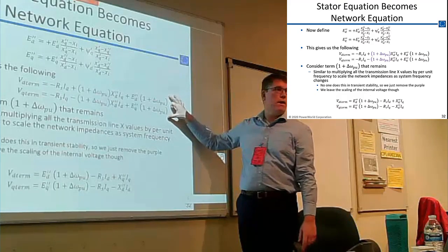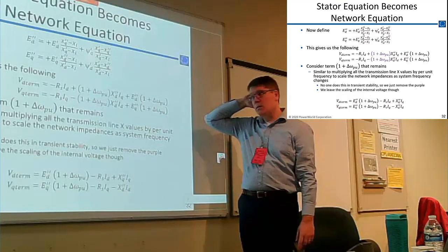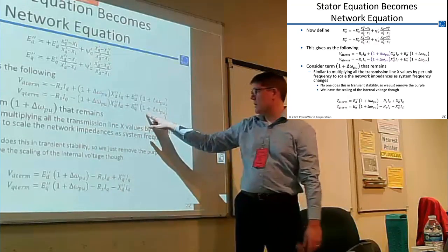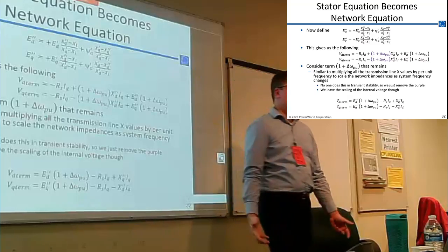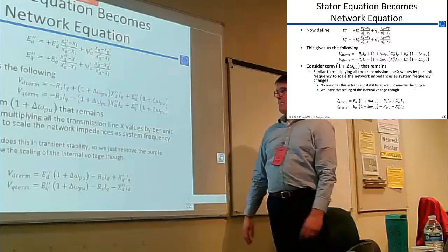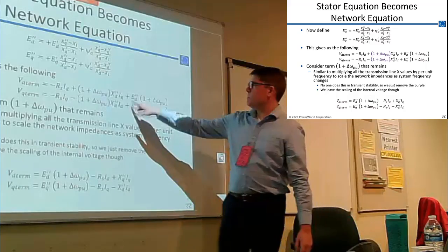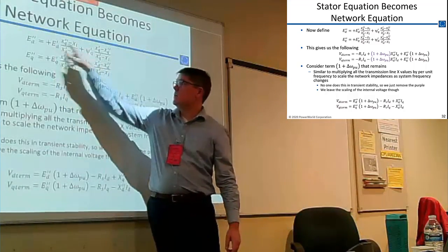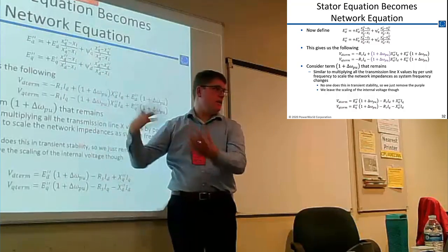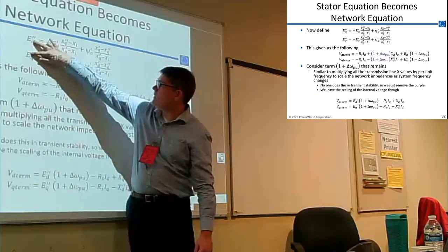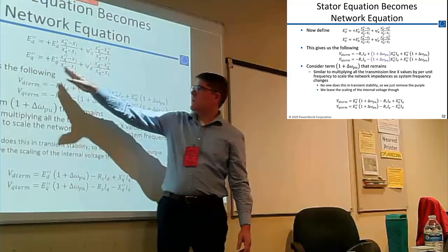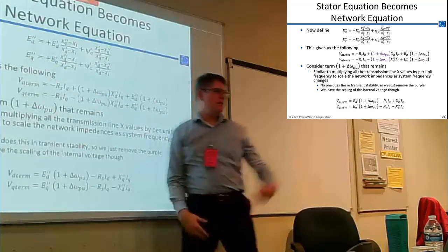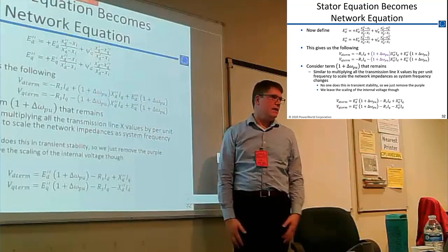So now we have these two terms here, where we're multiplying by essentially the per unit speed. Is the E a constant, or is it dependent on? No, these four values here are the fluxes inside the rotor, and they're changing. This definition is defining how these four fluxes are created to create some kind of a flux out on the stator, essentially. Okay. So they're changing. All right.